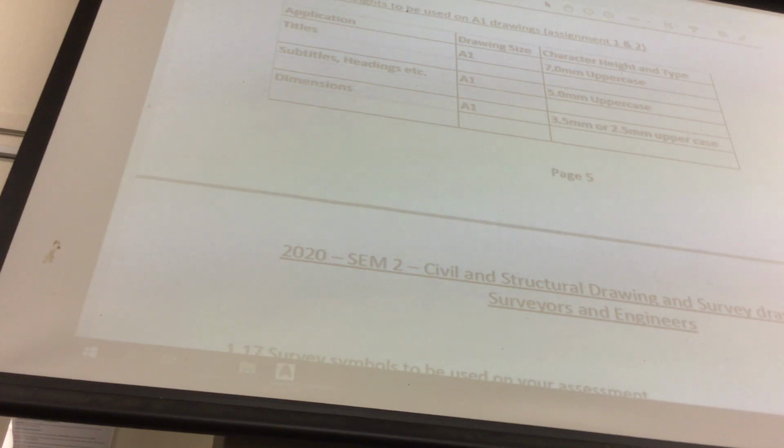Now, as a general rule of thumb, and here's another engineering note, anything that is above 1.5 meters will need to be engineered. There are standard wing walls online from different companies that make them, but once it gets above 1.5, to give you an idea, it's about here, on 1.8, so it's about there, right?